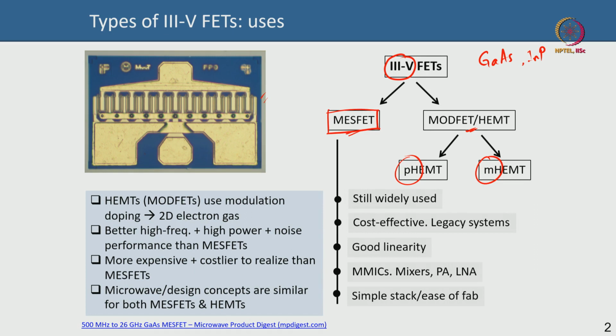You can see there are interdigitated fingers. So you can be assured that these are actually source and drain fingers. Each of these could be source, for instance, the other ones could be drain, and in between you will have the gate that runs. You need so many fingers to carry higher current because you need to deliver higher output power, and the metals are also thick because they should be able to carry high current. Okay? Only then can you get high output power.